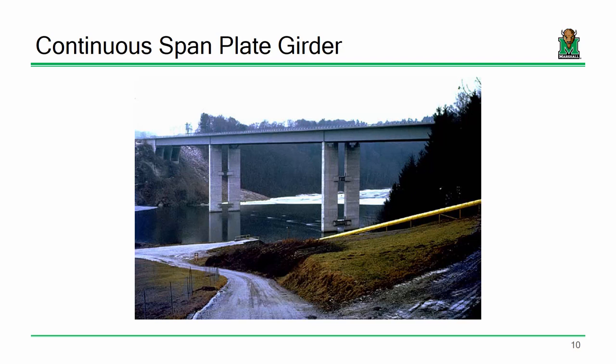If we talk about those negative bending regions, tell me, on top of that bridge is a concrete deck. That concrete deck, is it going to be in tension or compression? Right here. It's going like this. It's in tension. And concrete is a material that behaves very, very poorly in tension. So generally, if we start looking at these plate sizes and these beam sections, we're going to find much larger plate sizes right around the piers than we are in the main span, because the concrete is ineffective around that pier. So that's just some little points I want to make throughout this presentation.